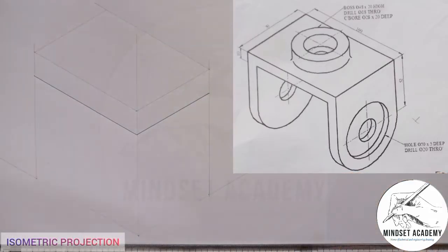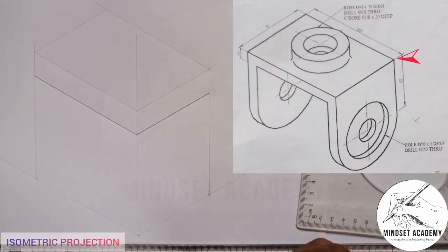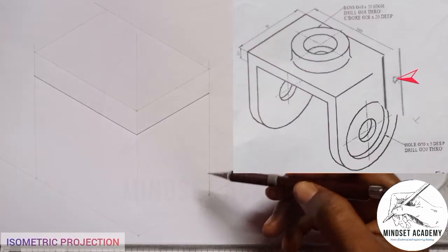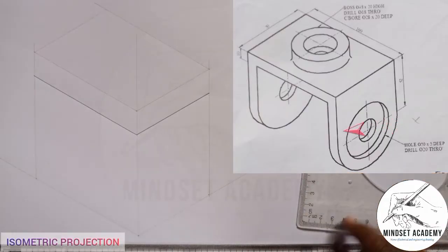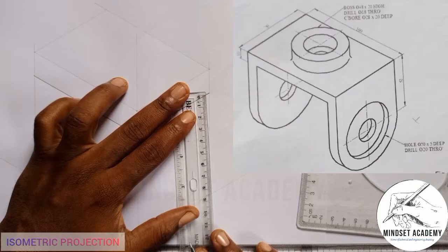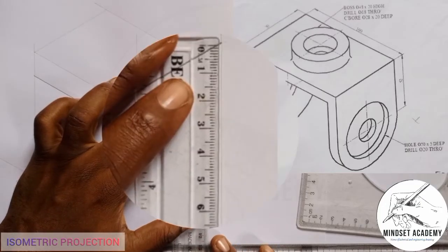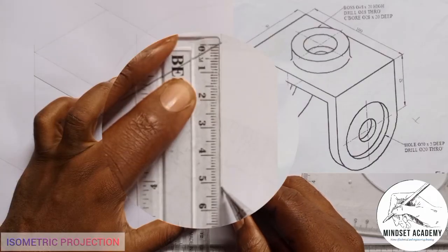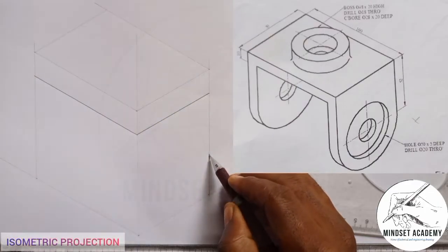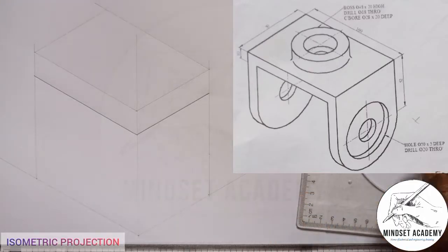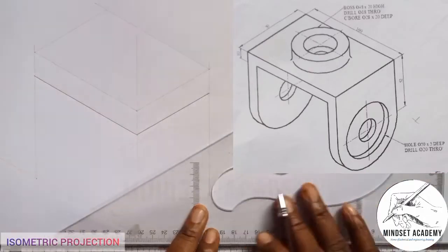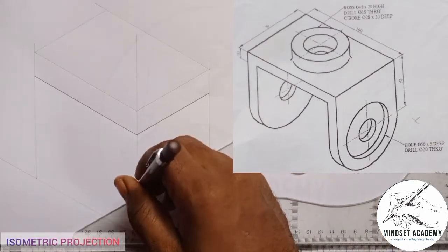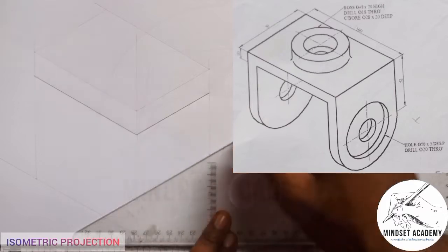Now we're told that from here to here is 52, which will represent the center of the circle you're seeing. So I'm going to measure 52. From 0 to 52, this is 50, and this is 52 here, right? And that is where I'll just transfer my point from this point to this point, meaning that this place will be the center of the circle that we need here. This is one of the centers here.